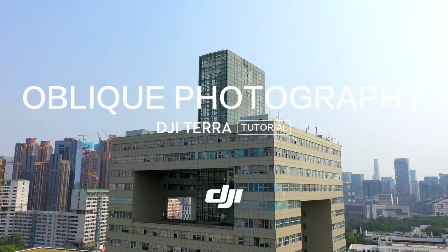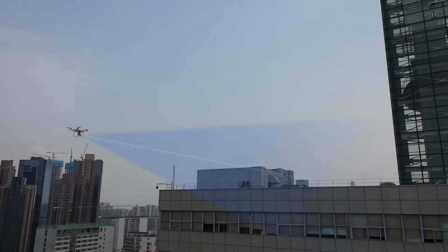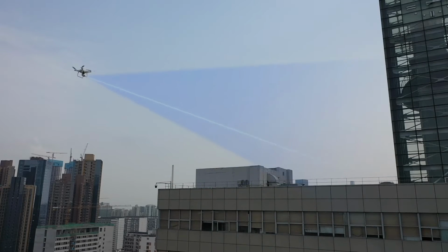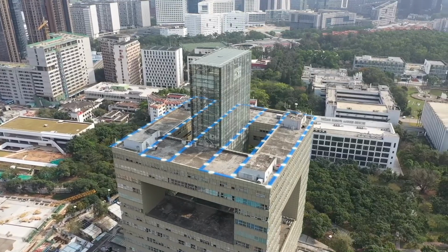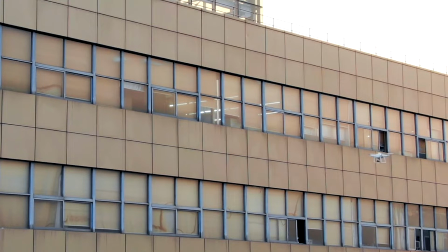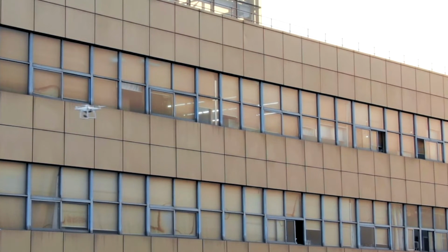How to use DJI TERRA's Oblique Photography Mission function. DJI TERRA's Oblique Photography Mission can automatically generate 5 different flight routes on the mapping area, capturing the downward, forward, backward, left, and right images to ensure the accuracy of 3D modeling. This following demonstration video will be carried out with the Phantom 4 RTK.